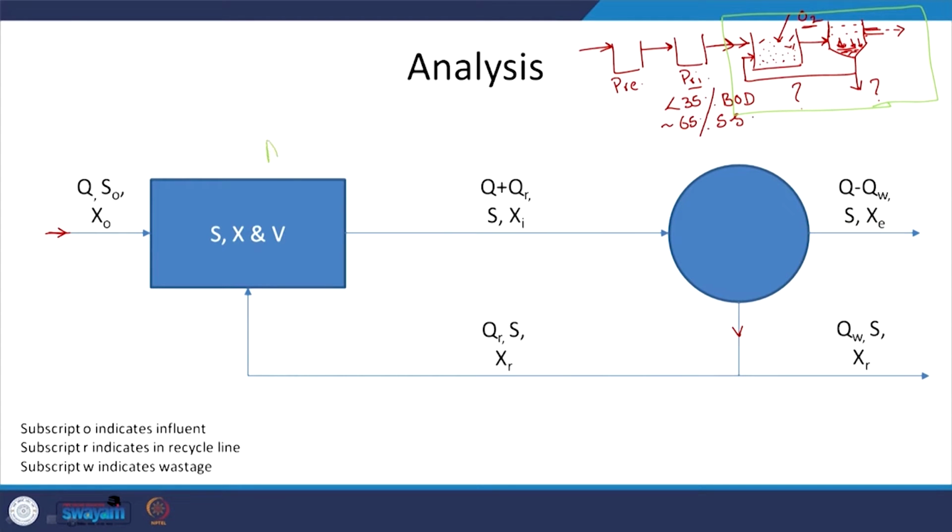So, this is the aeration tank. This I guess is a poor figure, but again you understand the typical shape that you want. And here you have the secondary clarifier or secondary sedimentation tank, where you separate the sludge or the microorganisms from your wastewater, which is easy to do because they are not dissolved obviously.